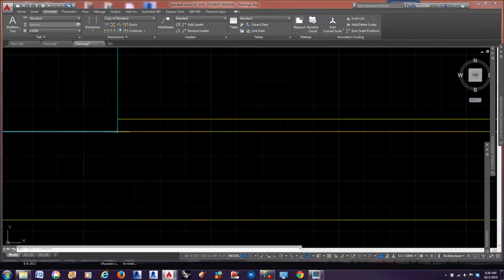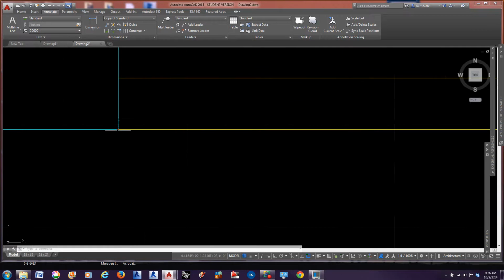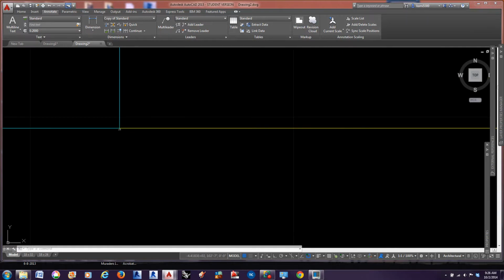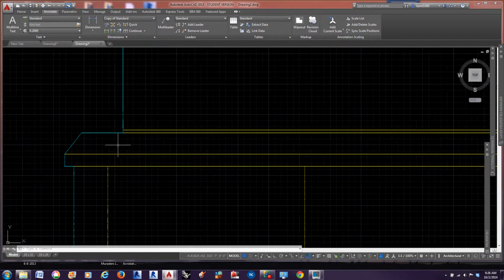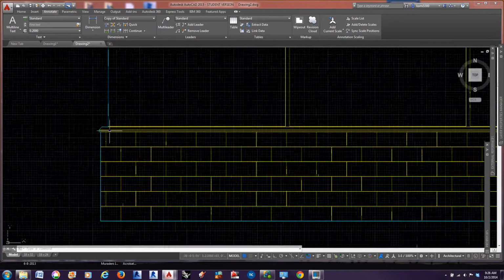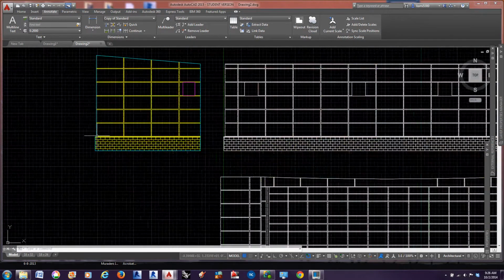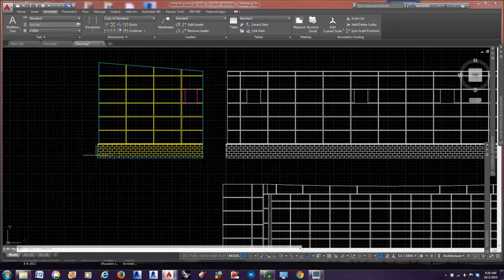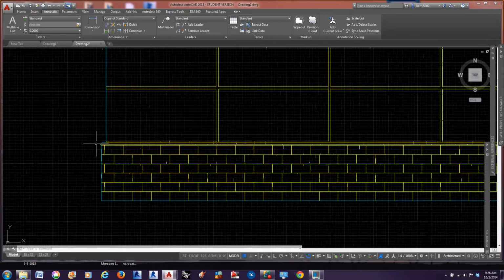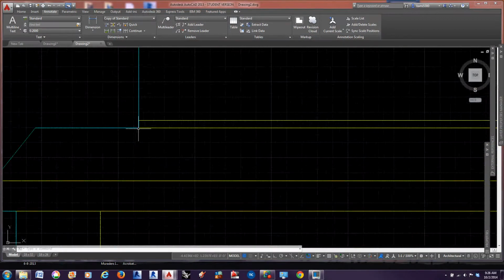And depending on your thickness of material, if it starts and stops right here at this corner, it'll sometimes not cut the object all the way out. Typically with chipboard it works well, that you don't have to join, but anything thicker